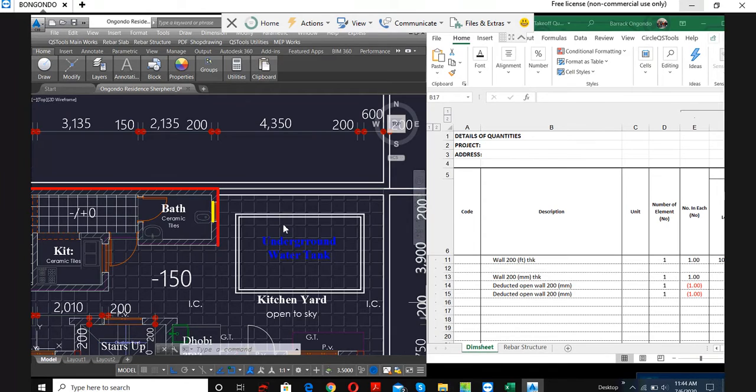When you're drawing a line from end to end, it means you're drawing the length of the wall. But remember, you've already put in the height. It knows walling is done in square meters. So it is going to read the length from the AutoCAD as you're measuring, and then it multiplies that length by the height you've put, then it gives you the area.